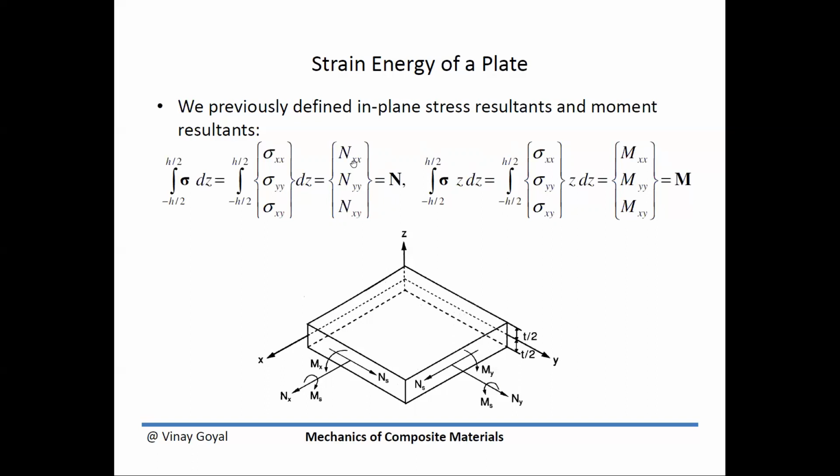Recall that these stress resultants are resultants acting inside the structure to react external loads. Just like stresses in a 3D structure are acting inside the structure to react the external loads. These are internal loads. Think about it in that manner. But we had to make the simplifications because we have simplified a 3D structure into a plate, and we only track the mid-surface. That's why these simplifications are occurring. And you may have never seen them before, except for the previous few lectures ago, which you can also find on YouTube.